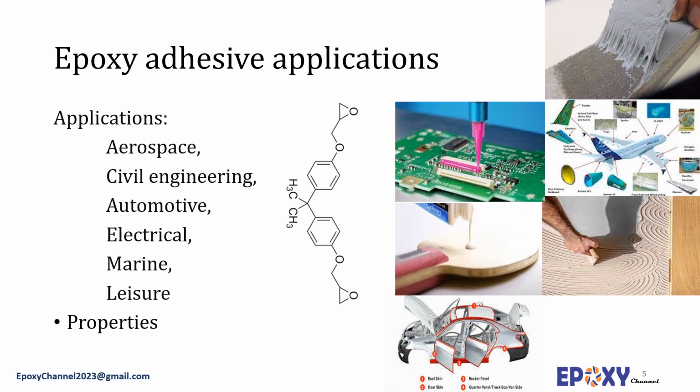For example, in their cure reactions, no volatile byproducts, for example, water, are produced. For the adhesives, this is crucial as there is no need to apply high pressure during the bonding operations. Moreover, if applied on well-prepared surfaces, epoxy adhesives often exhibit good weathering properties and relatively low shrinkage during the cure.